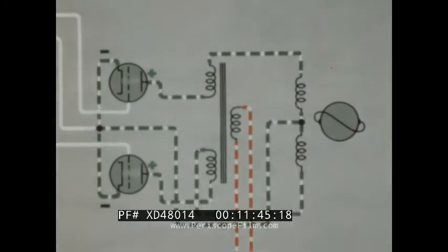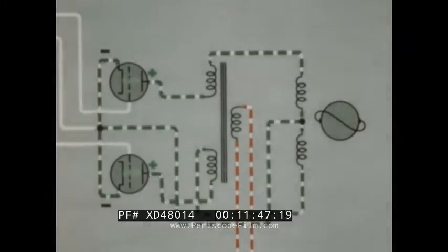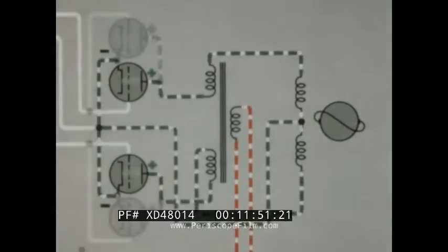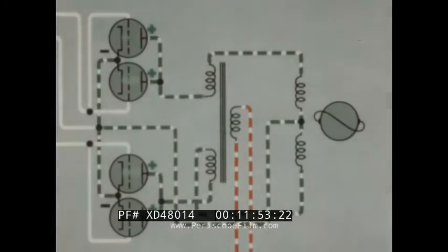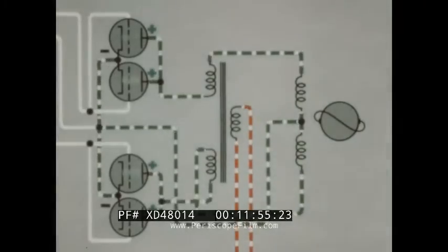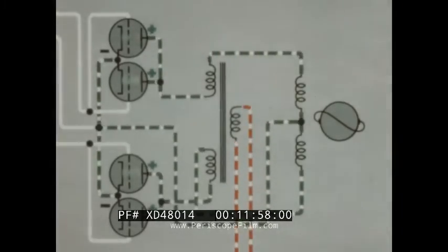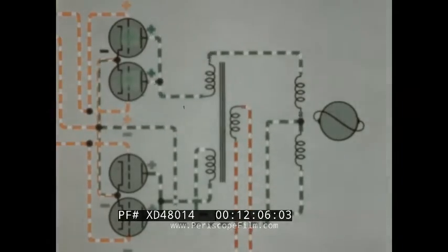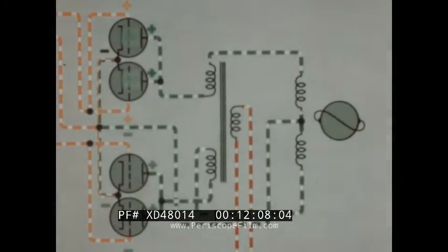In the basic circuit, one tube was shown for each direction of movement. Actually, two tubes in parallel are used. This is done in order to pass stronger currents through the amplidyne generator field coil. With a signal voltage applied to the grids of the tubes, the current will now flow through two parallel paths.